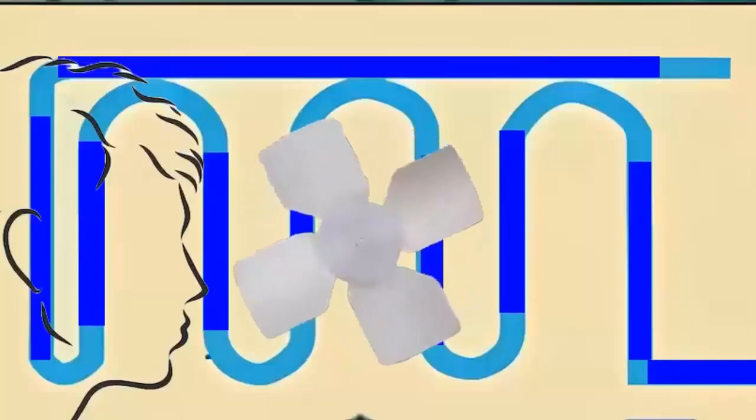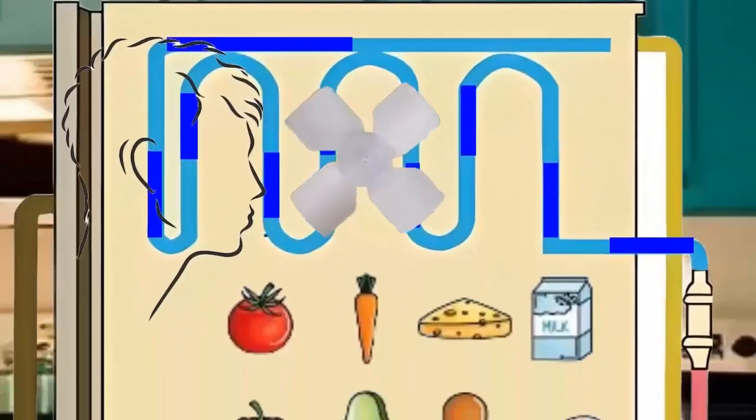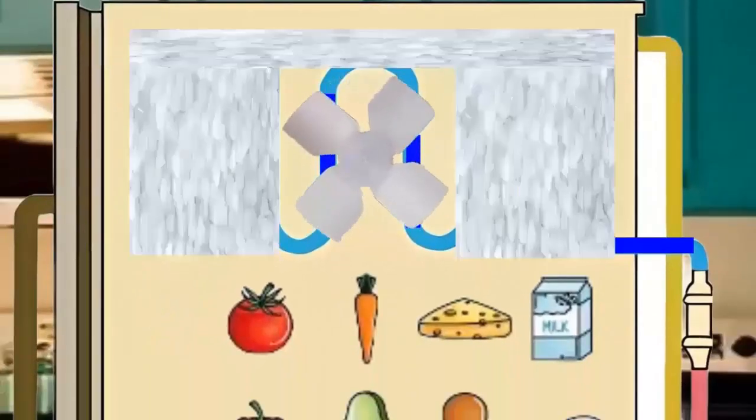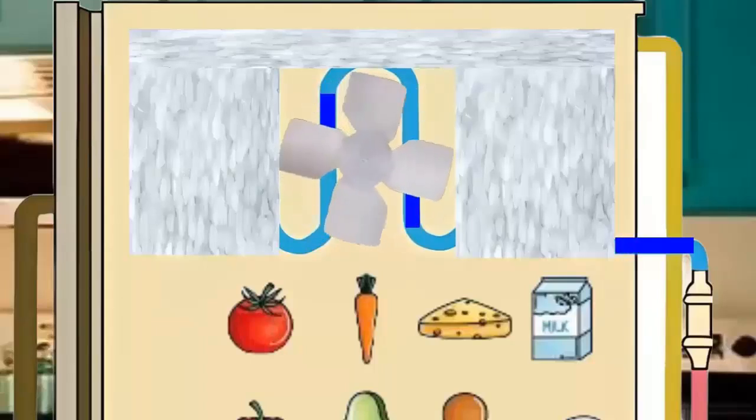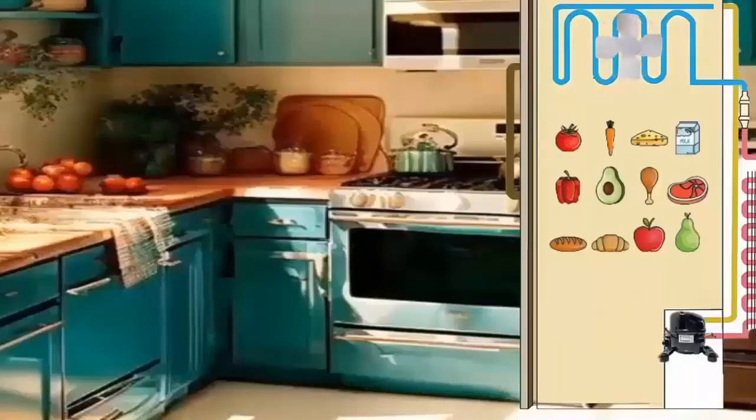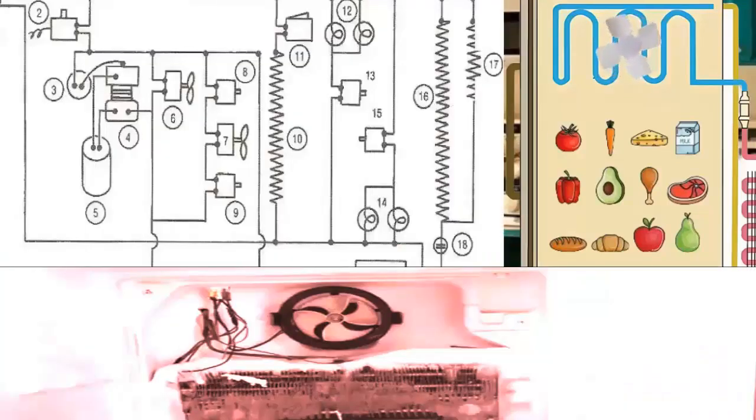Main causes of the issue. A. Lack of regular defrosting. Excessive ice buildup on the evaporator blocks the airflow from the freezer to the refrigerator compartment. This can be due to the defrost heater not working properly, or the control system, timer, or electronic board not activating the defrost cycle when needed.